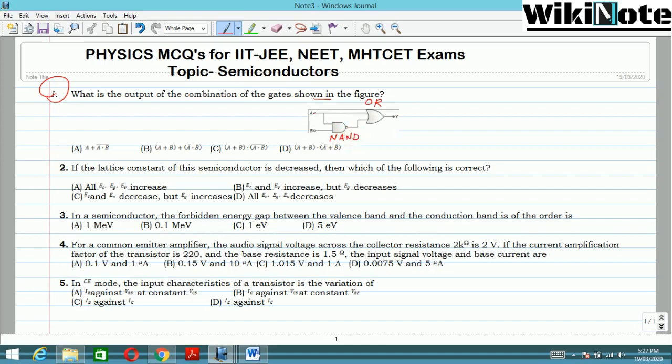So now A is coming over here as it is, so there is no other input here, so A is coming as it is as an input to the OR gate. And about A and B, I do have 2 inputs to this NAND gate. One is A and the other is B. So NAND gate output is always A dot B, that means A multiplied with B and the whole complement, which is this bubble sign, that is bar.